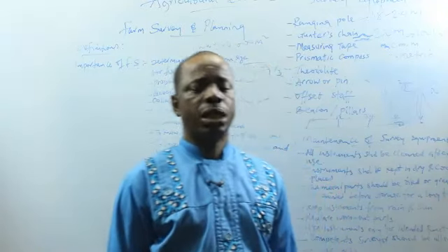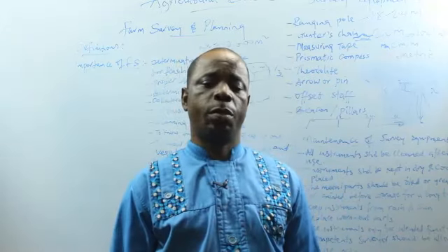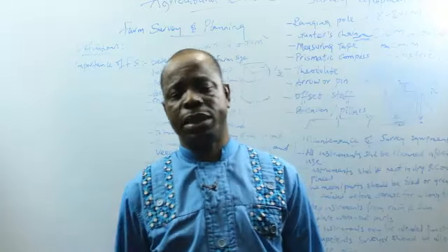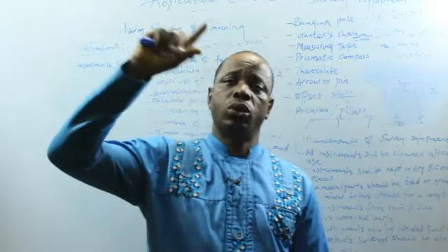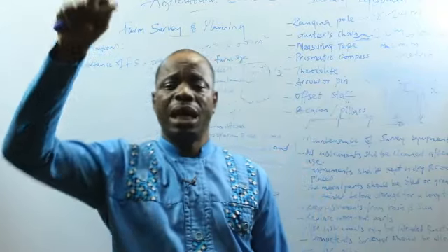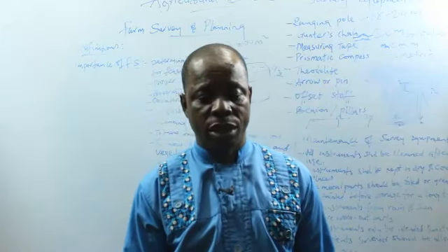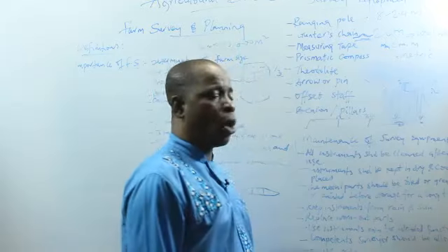What it means is that we can use theodolite to determine the bearing between 2 points or between 2 objects on Earth's surface, horizontal plane. It can also be used to get the angle of elevation between an observer and a plane, as well as angle of depression between observer, maybe, and a fish in the pond. These are vertical angles.